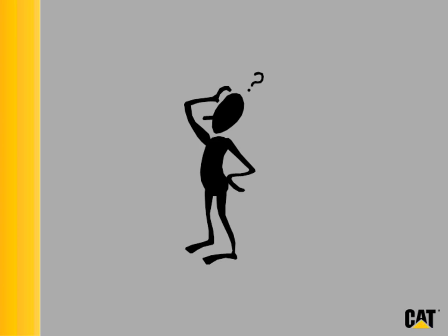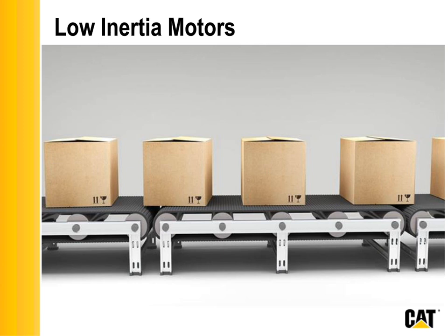Now, while we're talking about motors, what application doesn't have motors as part of its load scenario? You've got motors, you've got non-motors, you've got linear loads, you've got non-linear loads. Well, a lot of your application is going to have motors. And so if we're looking for another opportunity to reduce that inrush, remember with reduced voltage starters, we were able to reduce both the SKVA, the alternator, and the SKW, the starting KW, the engine. Well, here with low inertia motors, we're only able to reduce the SKW component of the inrush.